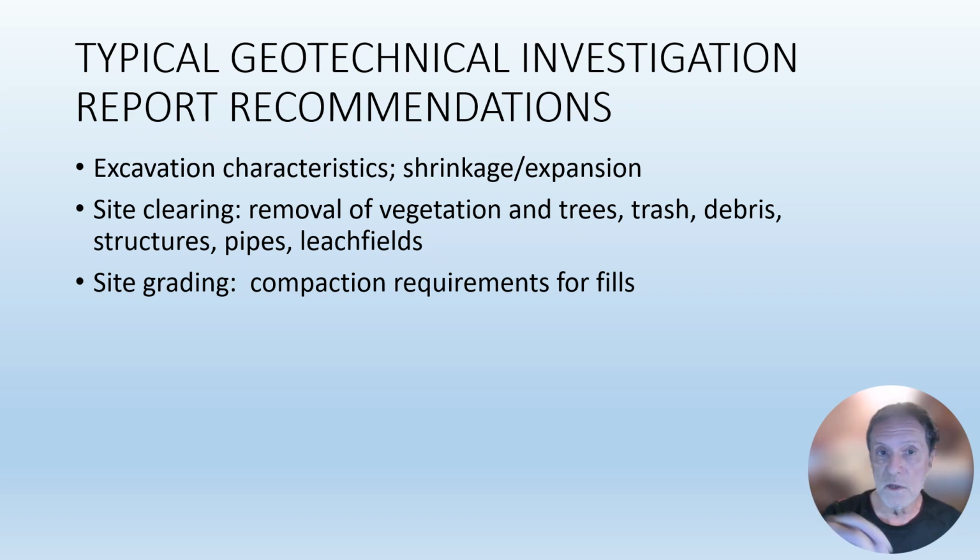It's important to get proper compaction of that filled material, and there are standards for compaction. You take a sample into the lab and run what's called a Proctor compaction test, and you do it at different moistures. If the material is too dry, it'll have a low density. If it's too wet, it'll have a low density. So you want to look for a maximum density and an optimum moisture content. So that's what you want your compacted fill to be, 90% of that maximum density under optimum moisture conditions. Usually clays will take more water than sands because they absorb more water.